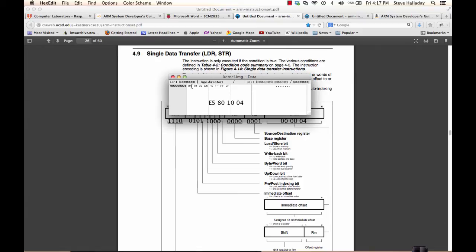We're going to need to do another store operation, but instead of storing a 4 like we decided down here, we know that we're going to have to turn on the LED, and so we're going to need to store this. Remember, this store instruction enables the GPIO controller. Then we need to actually write some data to it that will cause the bit to show up. In order to do that, we're going to write to address hex 28, the offset of hex 28 from the base address. So we can create that same instruction,